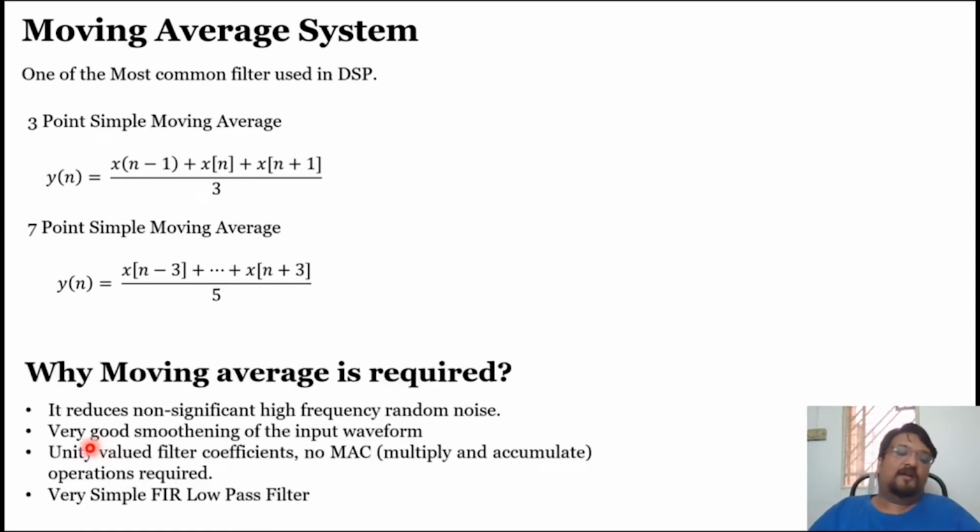First of all, most biomedical data sets are affected by high frequency noise. For EEG, ECG, and other signals, each has its own frequency region of interest. For EEG, we don't care about frequencies greater than 100 hertz or so. If your recording has a non-neural component greater than 100 hertz, it's very rare in EEG, and if it is there, we need to identify whether that signal is because of some artifact or whether it is a neural signal.